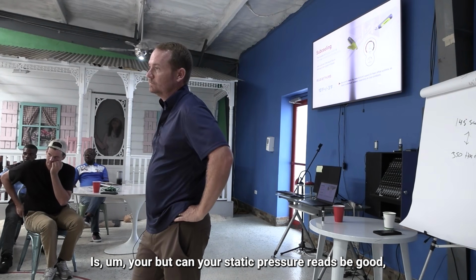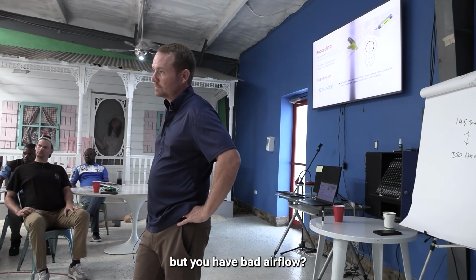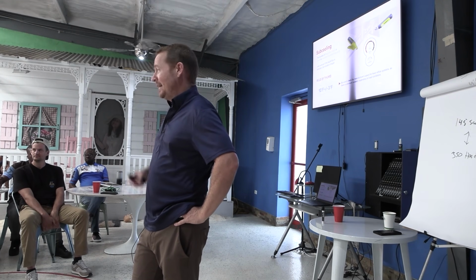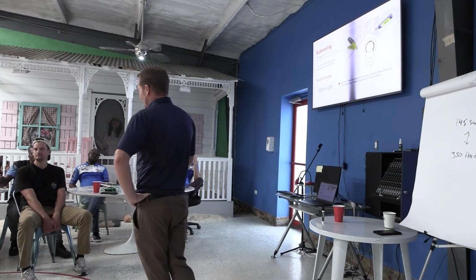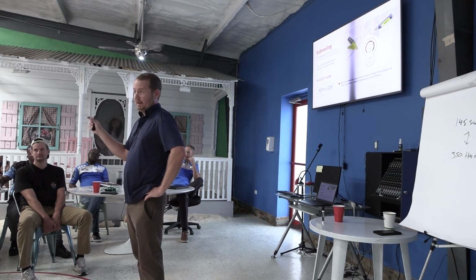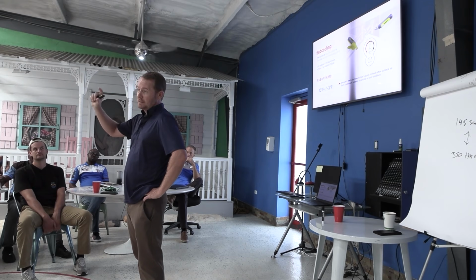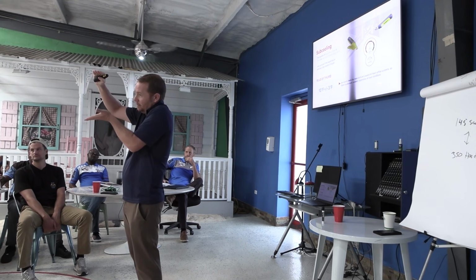We haven't reached here, but can your static pressure readings be good, but you have bad airflow? Yes, absolutely. Matt's going to talk about this, but since you asked the question, it's very important that you know this. First off, we're assuming that you're measuring it right, like you're putting it in the right spots. Especially when you're dealing with a newer tech, that's not a good assumption to make, right? You really care about what it is at the blower.